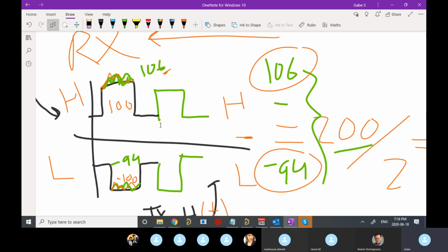But you can make your own UART, call it JART, and then Jared decides whatever he wants. Make it an active high start bit, and the line floats low, or idles low. I2C is the opposite of UART, I guess, in that sense. I2C has ACKs and NACKs and a bunch of stuff in there, which we'll talk about next week.